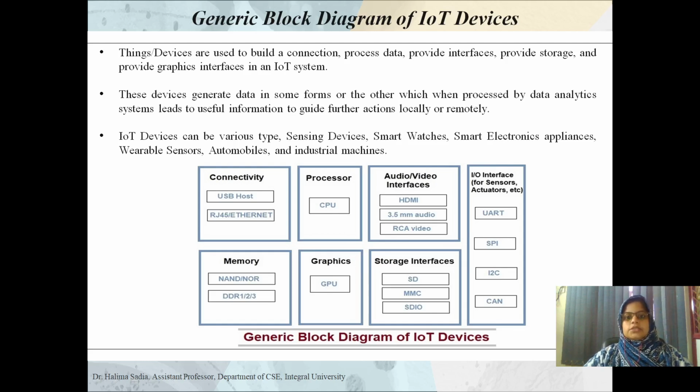The transmitting UART converts parallel data from a controlling device like a CPU into serial form. It transmits it over the communication medium serially to the receiving UART, which then converts the serial data back into parallel data for the receiving device.